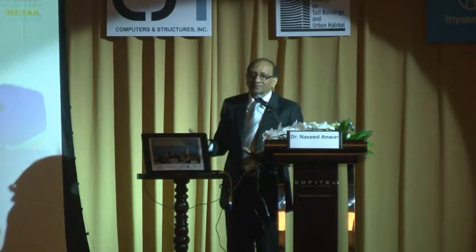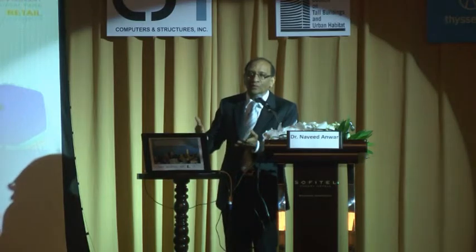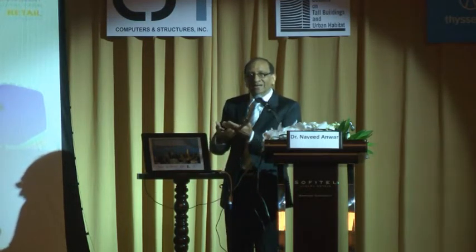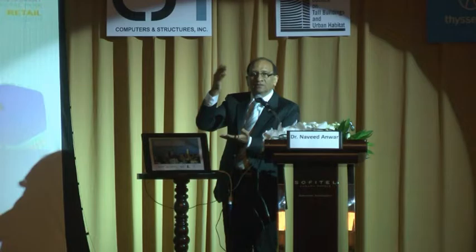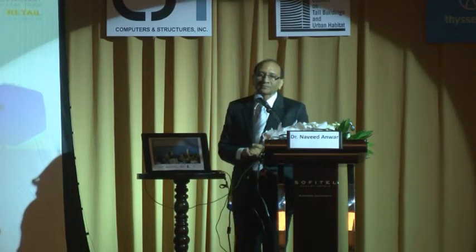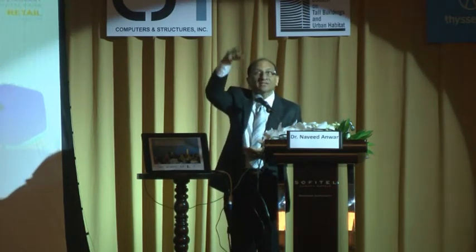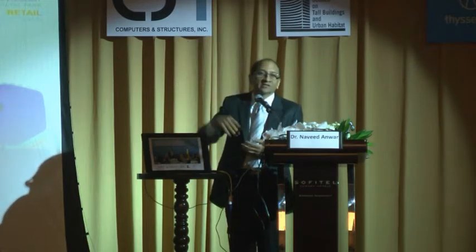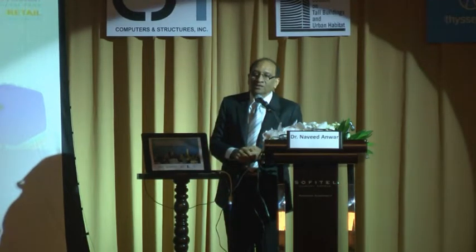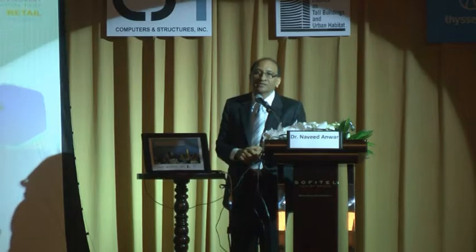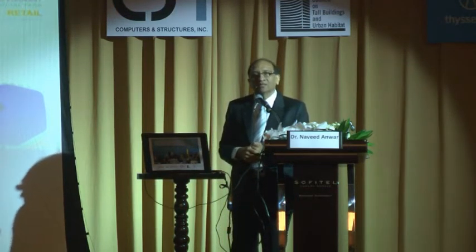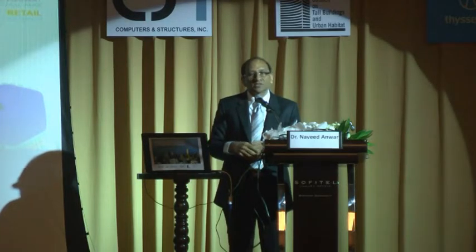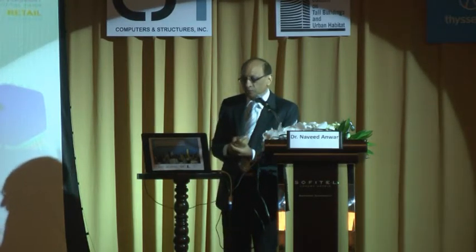Parking in a building becomes an issue. You need to park the cars, you need a certain width. So if that translates above, the plan above cannot be. And if there is a hall like this and there's a building on top of that, I'm sure there's a transfer mechanism somewhere. So every time the use changes, you get into trouble with the structural system, and that creates difficulties in especially lateral load resisting systems, ductility, and many other issues.